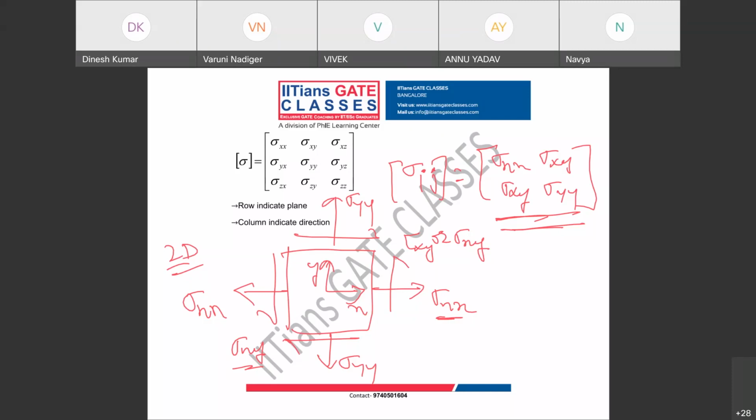All right. Now, guys, you know this stress system, and someone asked to find out principal stresses. You will be using some formulas, because you might have already studied those formulas. But here I will not use any formula. For this matrix, if you find eigenvalues, those eigenvalues will be your principal stresses.